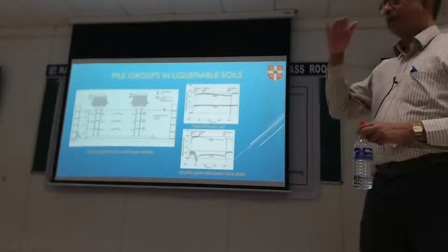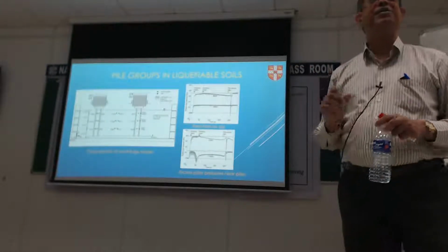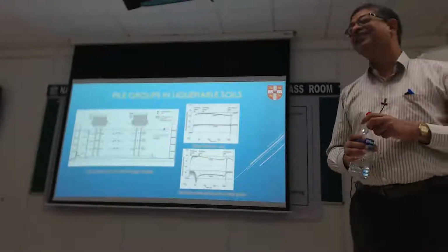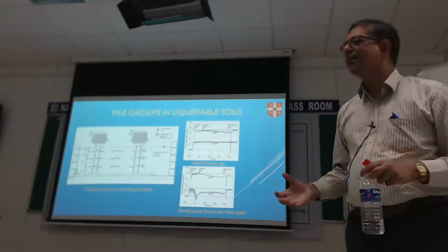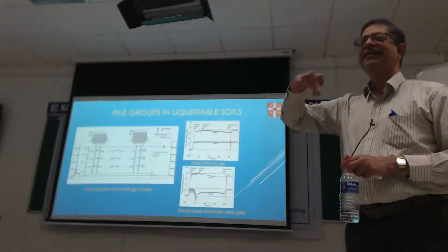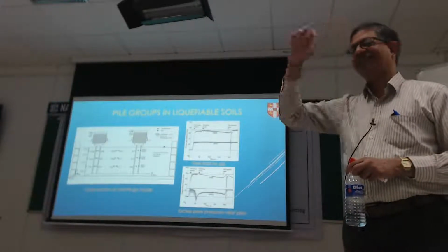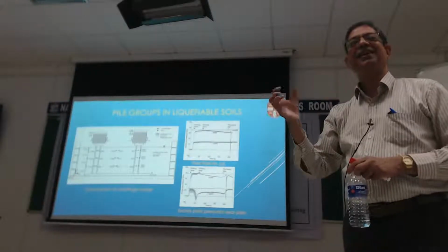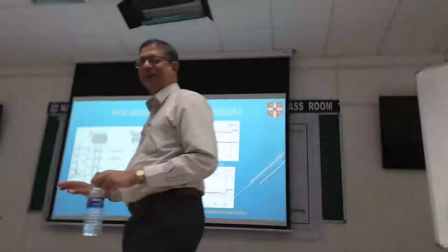Now, if I put a lot of load on the top and shake it, I need to worry about, from yesterday's lesson, inertial effects on the pile group. They become so big that it's like holding the head of the pile group and doing that. It'll just break its neck. Not very pleasant for the pile group.